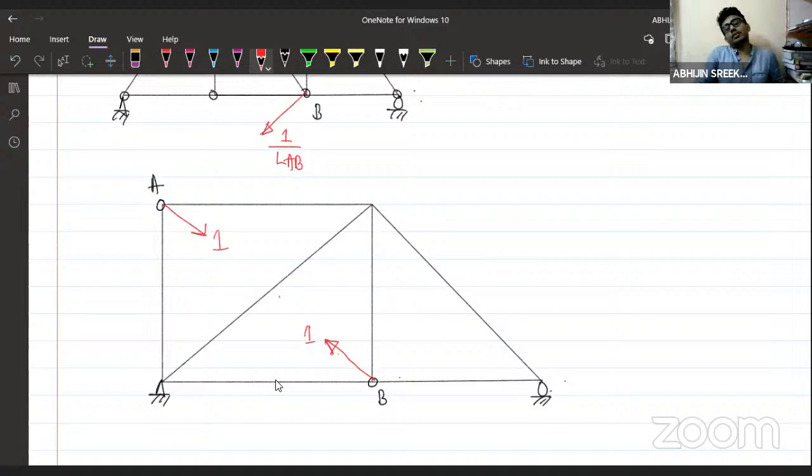And we will be finding the forces in various members, k_AB, k_BC, something like that. We will be calculating the force in every member, and ultimately we will use the equation ΣPkL/AE, or Σk·δ', or Σk·L·α·ΔT to get the answer here. If I'm getting a positive answer, the meaning is that joints A and B will move closer, towards each other. If I'm getting a negative value, the meaning is that they will move away from each other.